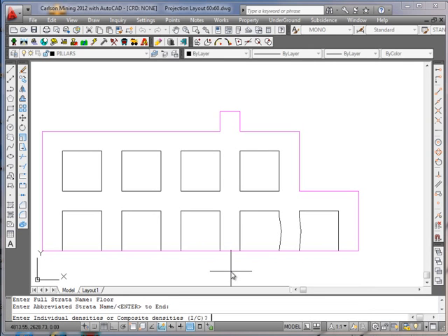And now we can enter individual densities. So you just type in an I, and then you'll be prompted for the density of the roof. If we're working in the English system here, it'd be 155 pounds per cubic foot. If you were in the metric system, it would be kilograms per cubic meter. For coal, we'd see roughly 80 pounds. For parting, it could be anything. I'll put in 145. And for the floor, I'll put in 160.